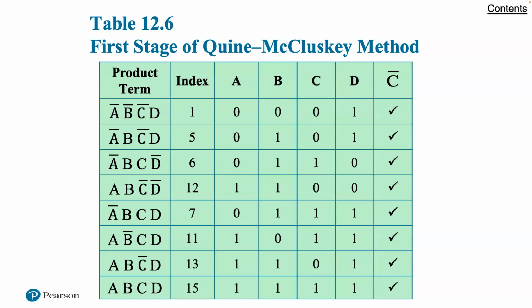The new table is organized into groups in the same fashion as the first table. The second table is then processed in the same manner as the first. That is, terms that differ in only one variable are checked, and a new term produced for a third table. In this example, the third table that is produced contains only the term BD. In general, the process would proceed through successive tables until a table with no matches was produced. In this case, this has involved 3 tables.